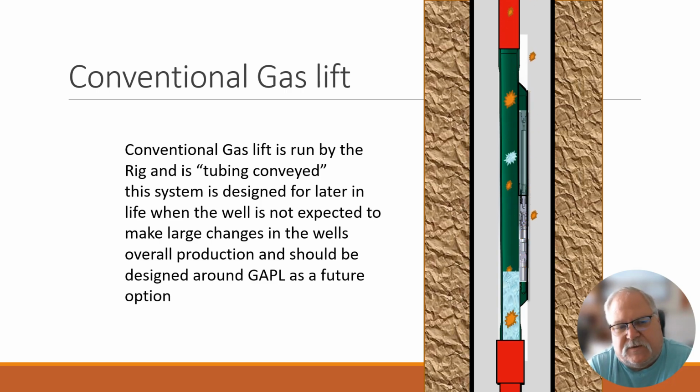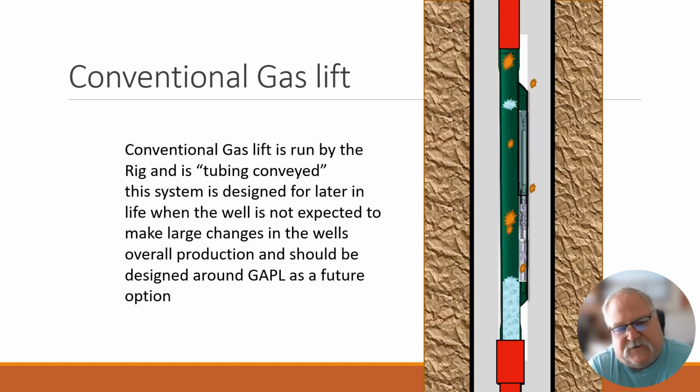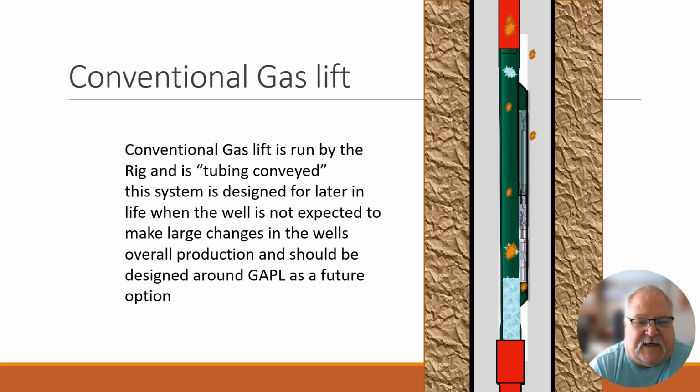If you're below the liquid volumes required for true gas lift, then you move into what's called deliquification, where we got to inject enough gas to basically get the tubing rate above critical. True gas lift is not about being above critical rate, it's about gasifying the liquid. It's a GLR manipulation. Once you move into deliquification, because you don't have enough liquid to foam to get to surface so it can be pushed out by the well, you need to replace that liquid with gas, and you need to come above critical velocity in order to sweep that liquid to surface.